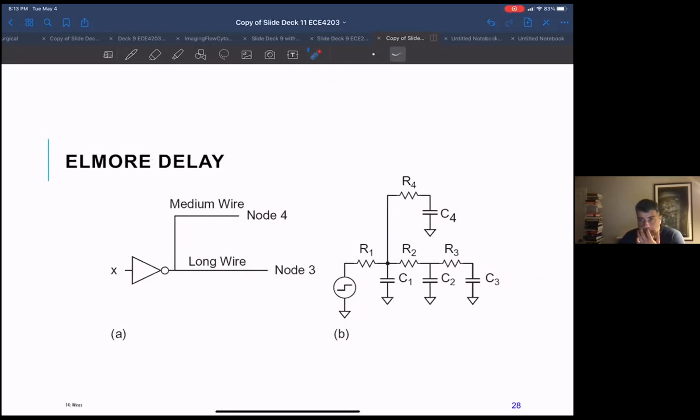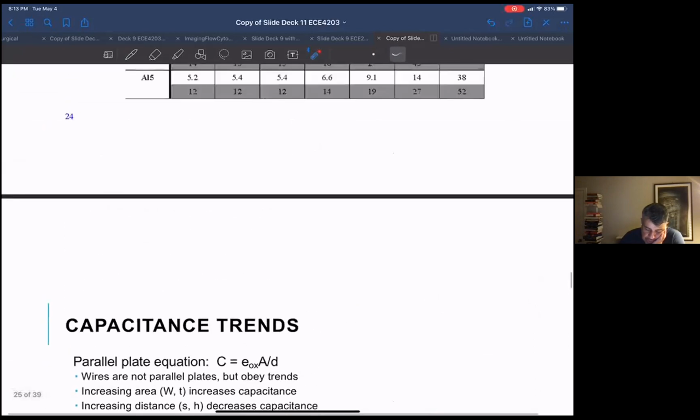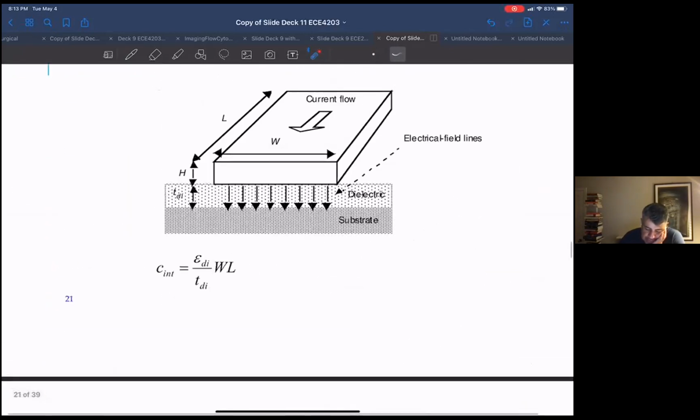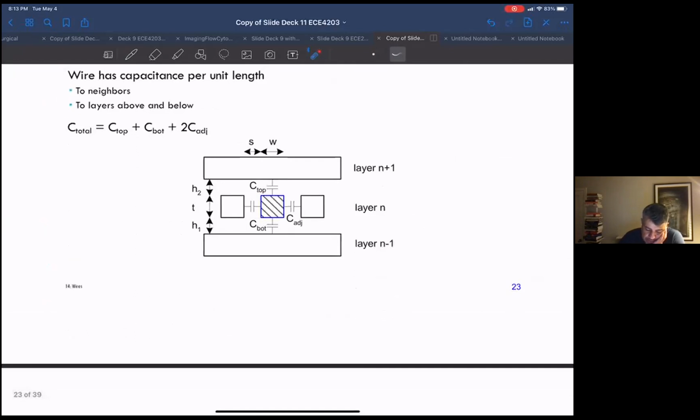Now, another problem that capacitance gives you is crosstalk. In a fantasy scenario, you just have a metal line sitting over a substrate. In reality, you have a metal line sandwiched between a bunch of other metal lines, which potentially have their own signals running through them, and some of these may be high-speed signals.